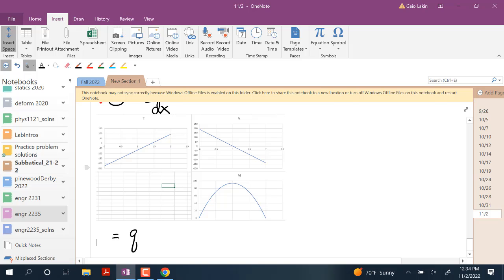What can we say about the risk to this thing? Not too much, because the shear force and the bending moment kind of have opposite stories. If the thing is really susceptible to bending, then the middle is where it would break. If it's really susceptible to shear force, then the ends is where it would break. There are some materials like bone, for example, that is really good at resisting compression, but not very good at resisting tension, because when do you ever need that? You know what I mean? And so even though it goes up to a lot of compression here, you might be more worried about it there where it's in tension.